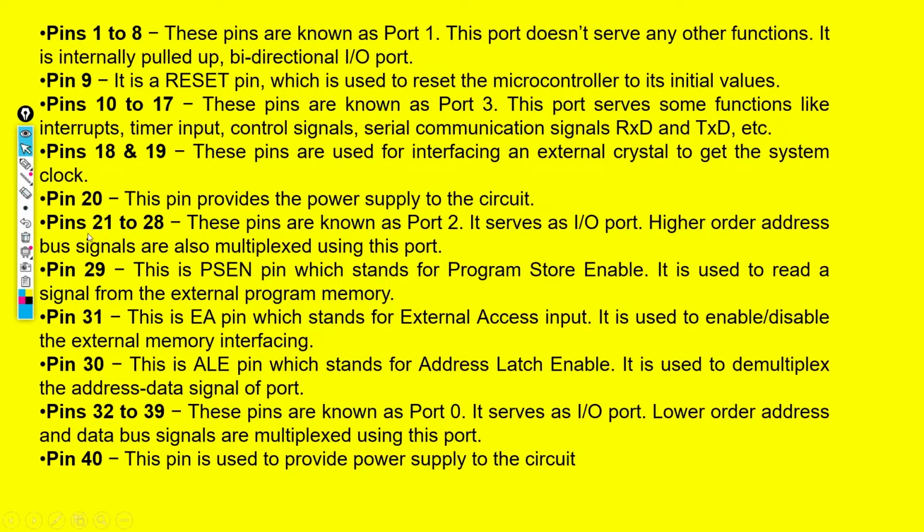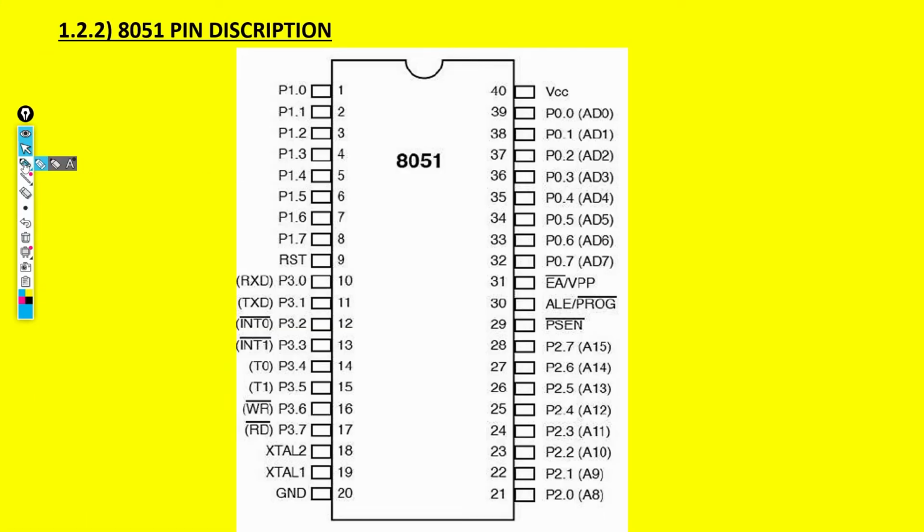Port 20 to 28, these pins are known as port 2. It serves as input output, and higher order address bus signals are also multiplexed using this port. This is also not a simple port.